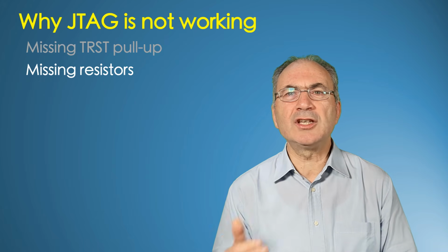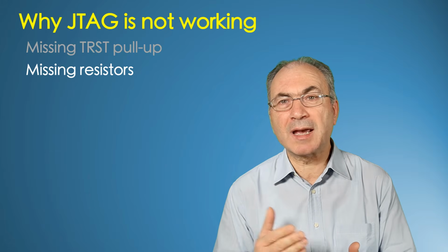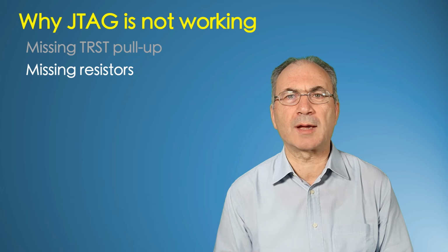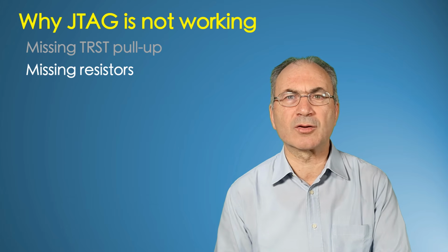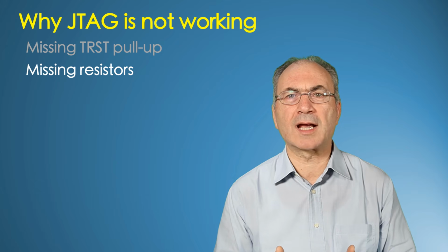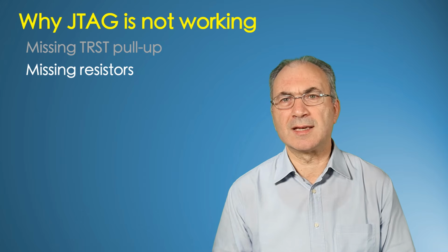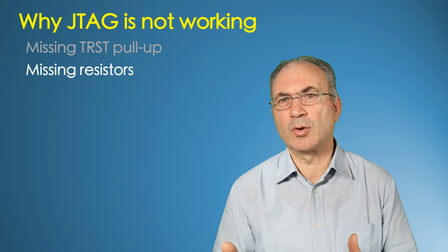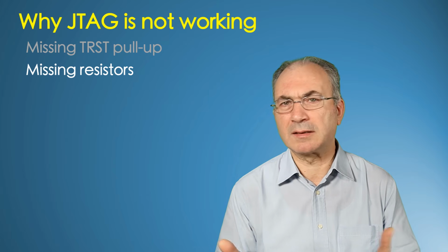Usually between each JTAG connector pin and the related system-on-a-chip pin there is a low-value resistor that can be missing during mass production and can be included only in the prototype boards. This issue can be solved putting back the resistor or making a direct connection, short-circuiting the resistor pads. In this case, we'll eliminate a small protection for the system-on-a-chip pins, but it will function.